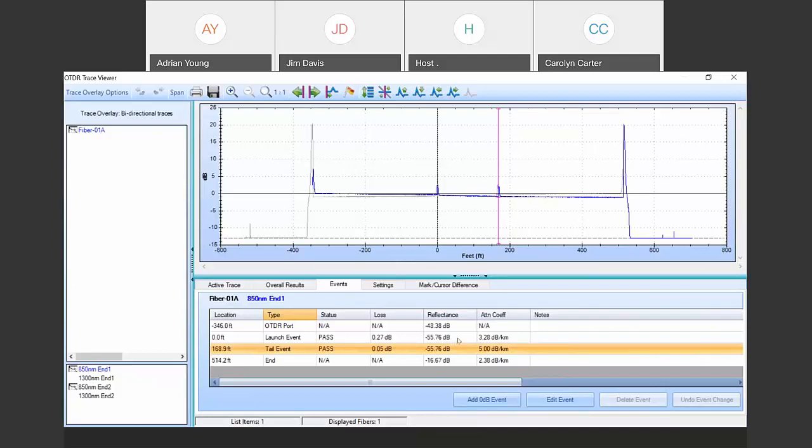Yeah, I will just back up Jim on that. When you come to OTDR testing, particularly with the reflectance, your less than perfect cleaning practice that you got away with using a power meter and a source really starts to show up when you start looking at reflectance. But as Jim said, absolutely get that LinkWare file, send it to support@flukenetworks.com, and we have a great team there, and they'll be able to analyze it and give you some pointers as to why it's failing and what the possible causes are.